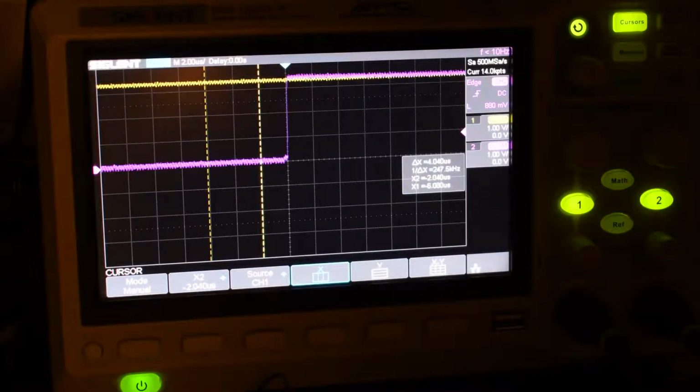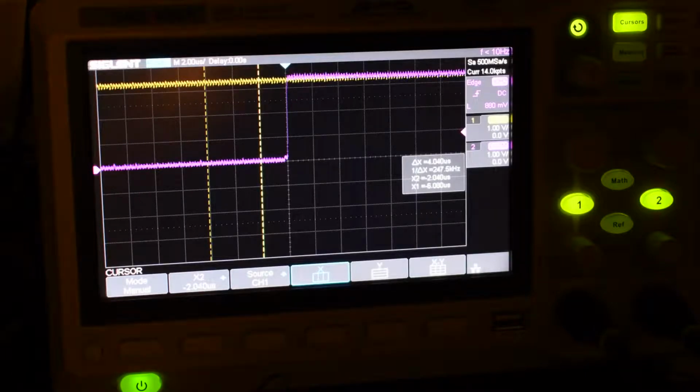So I'm going to start by resetting the whole thing. So I'm going to connect the reset wire to the high voltage and then just release it, and that 50 ohm resistor will pull it back down to ground, and that'll start the counters counting.